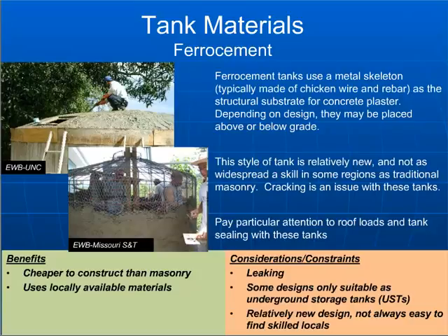The ferrocement tanks, these are very interesting. A lot of EWB chapters have employed ferrocement tanks. Some people swear by them. Some people tend to be rather skeptical of them. I think the most important consideration for ferrocement tanks is that you really do need some skilled labor or somebody that knows what they're doing. There are very tight tolerances on the construction process, and if mistakes are made at any point along the process, it's very easy to get cracks and leaking.